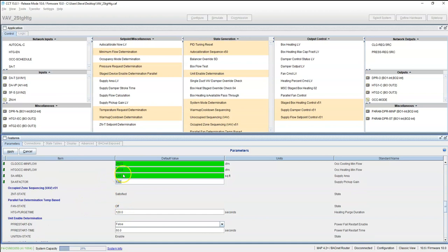If it's a 10-inch box and you have the 8-inch settings in here, it's not going to work right until it's fixed. And it's going to drive the TAB guy crazy if he is coming behind you because nothing's set right. It's going to be some far out there K factor because you don't have the size of your box set right. So set the size of your box.